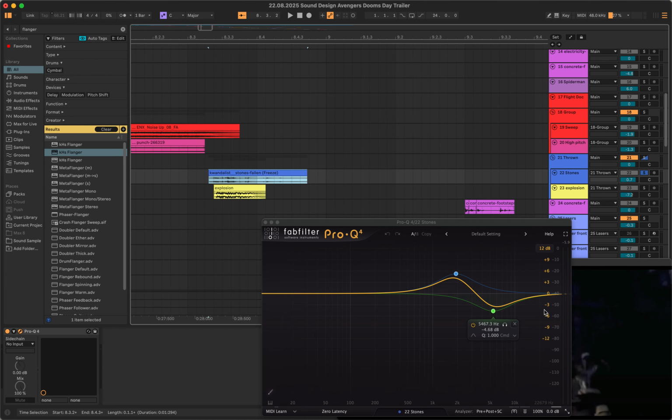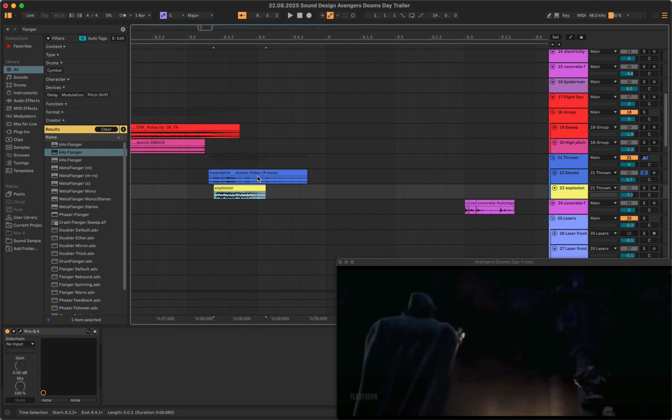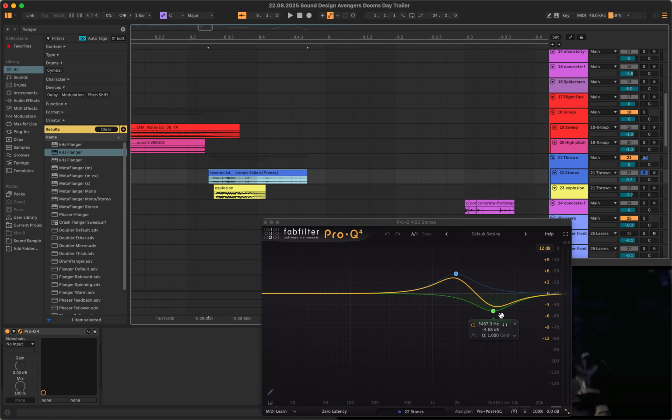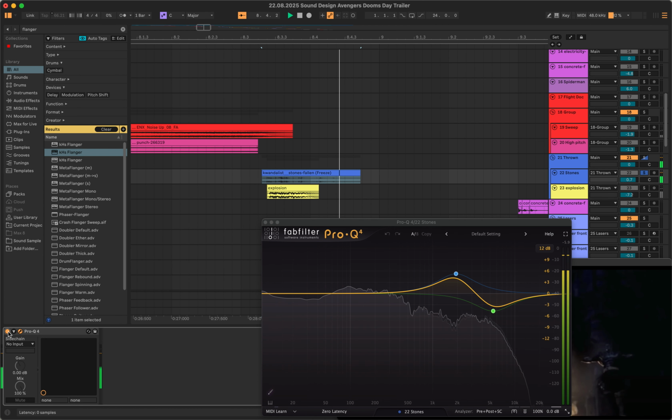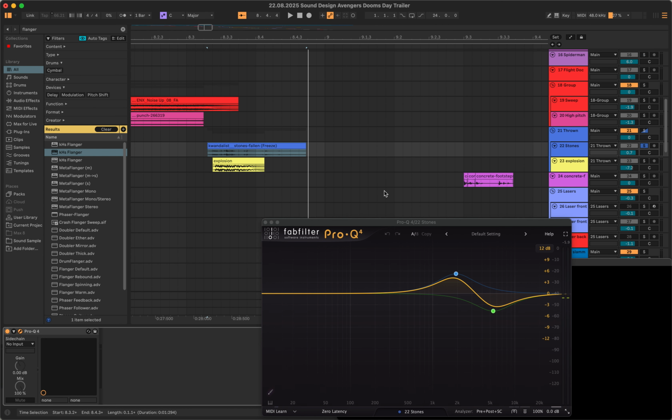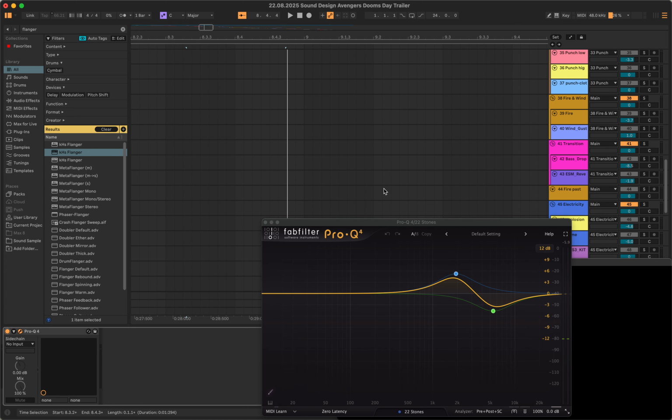This one I slightly changed like that to boost between 1 and 3 kilohertz. The sound between them is the easiest to listen to because it's similar to normal human voice frequency. So I exaggerated that and then decreased some kind of sharp sound at 5 kilohertz so that it's softer. With it and without it. Just slightly, but I think for me it's clearer to hear.